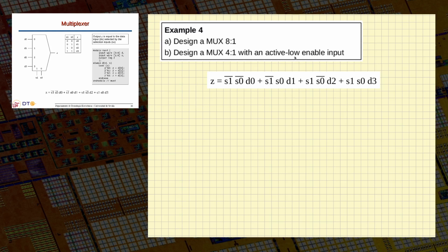Actually, we don't need that because we already know that the multiplexer is a selector, so it corresponds to this function. This function we can obtain not by simplifying a Karnaugh map, but by thinking about the specific operations of a multiplexer. So we build that expression so that when S1, S0 are equal to 0, 0, okay, then only this term will activate because this